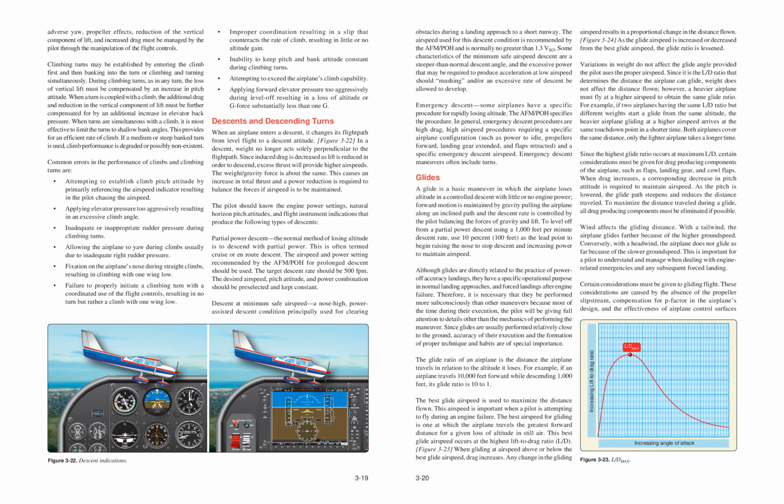Adverse yaw, propeller effects, reduction of the vertical component of lift, and increased drag must be managed by the pilot through the manipulation of the flight controls. Climbing turns may be established by entering the climb first and then banking into the turn, or climbing and turning simultaneously. During climbing turns, as in any turn, the loss of vertical lift must be compensated by an increase in